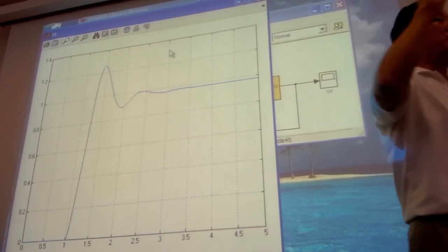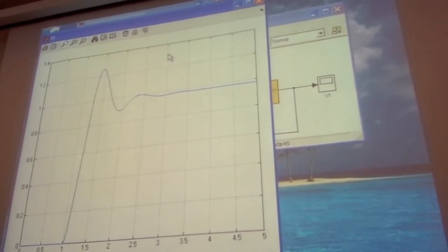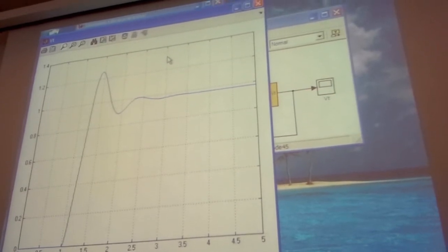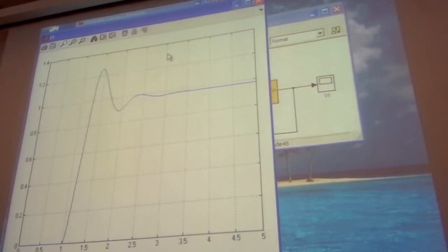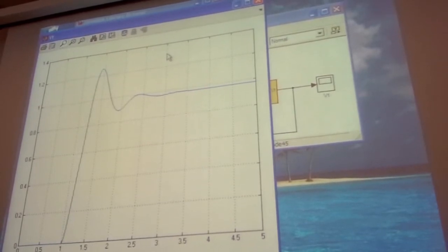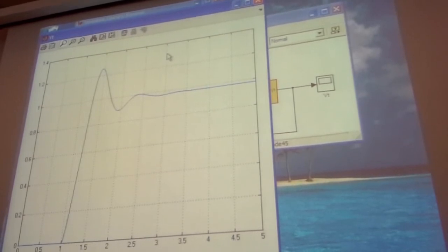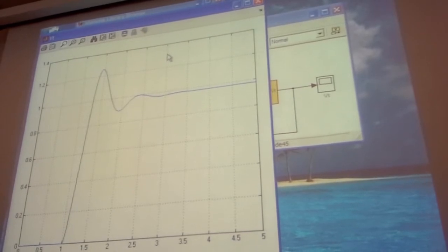That is the only bad thing. When you have a closed loop, that is a good thing, because you don't have to adjust manually. It automatically does that. On the other hand, two bad things: it can have some steady state error, and another one is, it can be unstable, because it's a closed loop. So we'll see later.